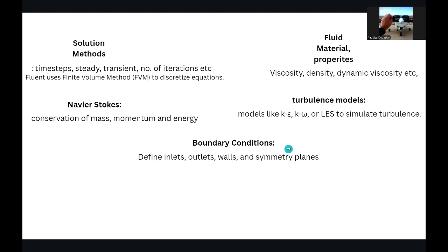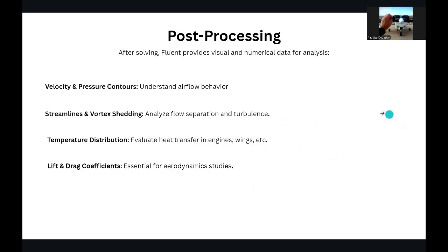Also, in boundary conditions, you enter the properties of the inlets and outlets. For example, the velocity of the fluid flowing in the pipe from the inlet is, let's say, 10 meters per second. So I have to put that in. Most of the models that you see here are second degree equations. That means they require two boundary conditions, in this case inlets and outlets. So you have to define the inlet along with the properties of the inlet, but also you have to define the outlet along with the properties of the outlet.